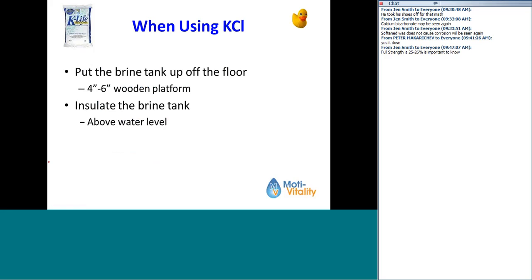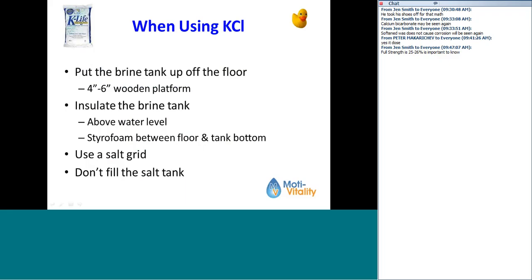Insulate it above the water level. Put styrofoam between the floor and the tank bottom, and use a salt grid. And another tip is don't fill the salt tank all the way up, so that you don't have the weight pressing down on it. Fill it only about halfway.